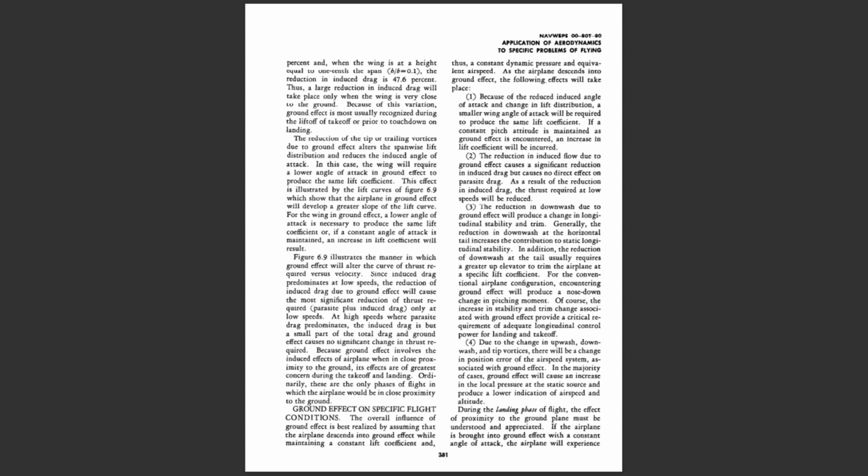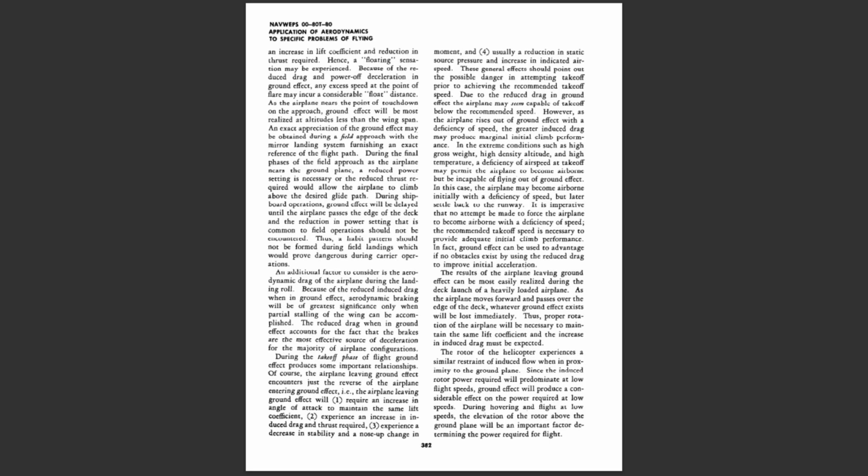During the landing phase of flight, the effect of proximity to the ground plane must be understood and appreciated. If the airplane is brought into ground effect with a constant angle of attack, the airplane will experience an increase in lift coefficient and reduction in thrust required. Hence, a floating sensation may be experienced. Because of the reduced drag and power-off deceleration in ground effect, any excess speed at the point of flare may incur a considerable float distance.